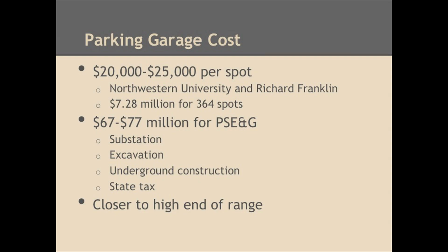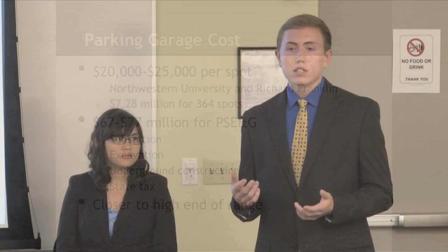For the cost of the parking garage itself, we decided that the cost of construction can be modeled based on the number of spots, with the value being between $20,000 and $25,000 each spot. This data was originally found from Northwestern University and was then confirmed by Richard Franklin, an employee of PSEG Services Corporation. With 364 planned spots in this project, the total cost should come out to around $7.28 million.